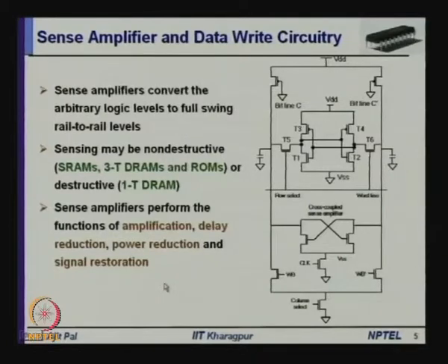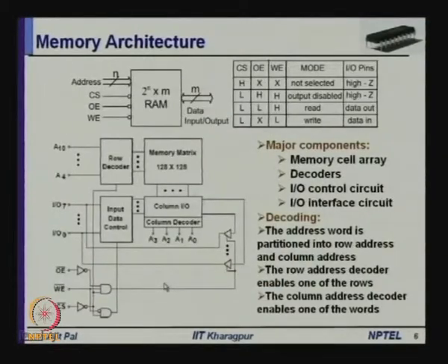Okay. So, with this discussion, as we are following a bottom up approach, now let us consider chip level. It is not a single bit. Whenever it is packaged in a chip, you have got a large number of bits. So, memories can be organized in the form of bits, bit organized, say 256 bit, or it can be organized in terms of words or bytes, say 4K into 8 bit. In this case we shall call it byte organized.